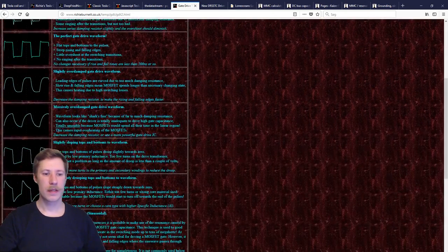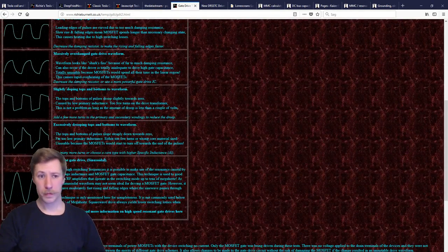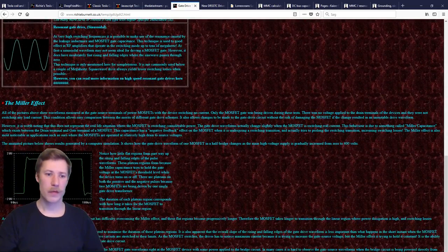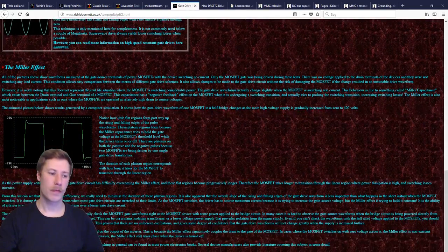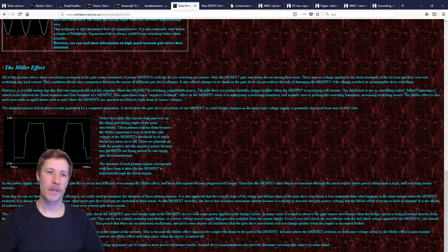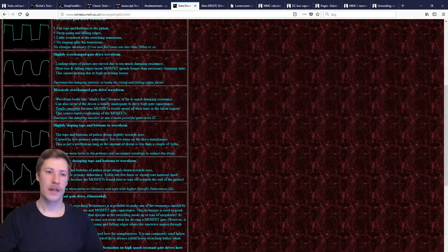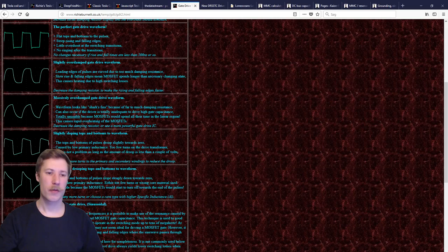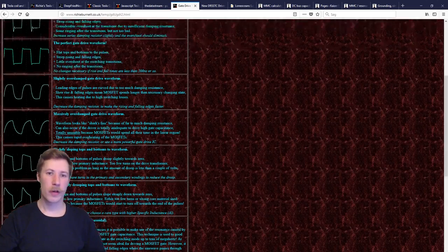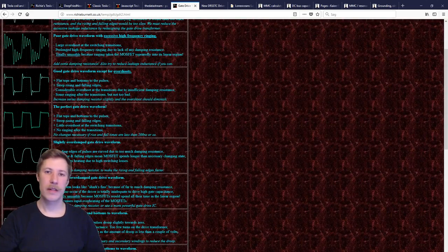So this is an absolutely golden source when it comes to debugging your gate drive when you think you have troubles there. And that is also very common, that you have some trouble here, either from using a wrong gate drive transformer material, or too few turns, or drivers that are not fast and powerful enough to drive the large IGBT gates that you are trying to drive.